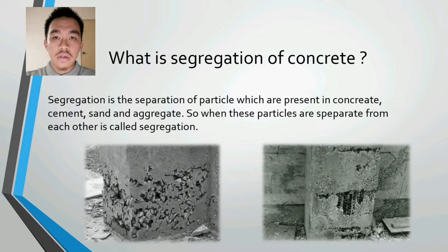Number 3, what is segregation of concrete? Segregation is the separation of particles which are present in concrete: cement, sand, and aggregate. So when these particles are separated from each other, it is called segregation.